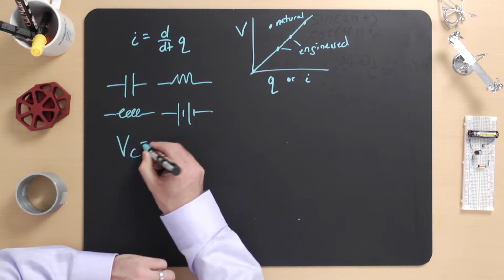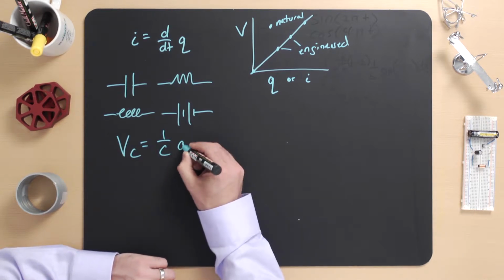Moreover, the relationship between voltage and charge of a capacitor is always a line represented by the constitutive law V_C = (1/C)Q, where the positive number C is called the capacitance. This means that the larger the capacitance, the less voltage V is required to maintain the charge. This is why C is in the denominator.